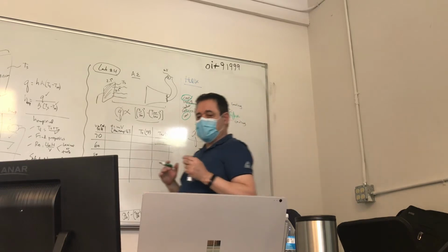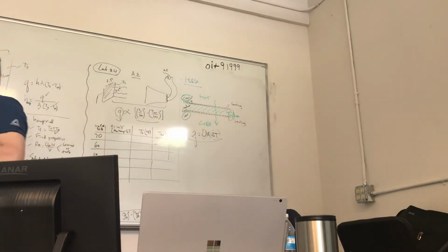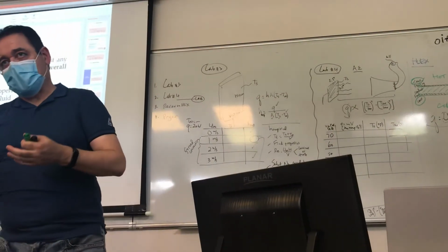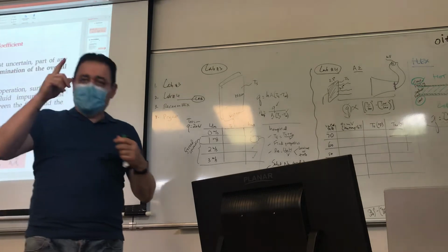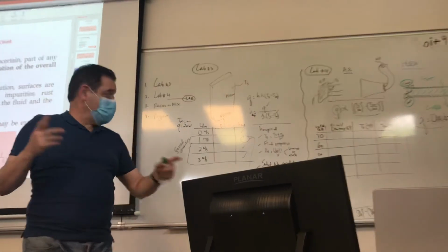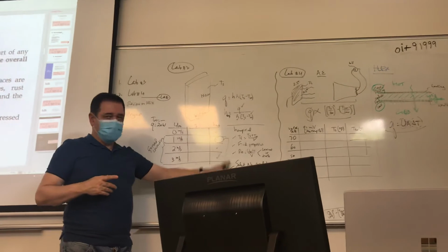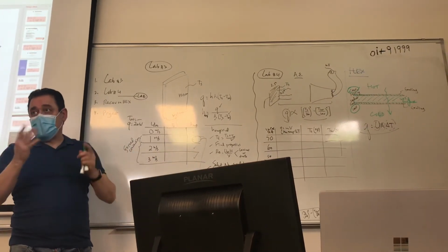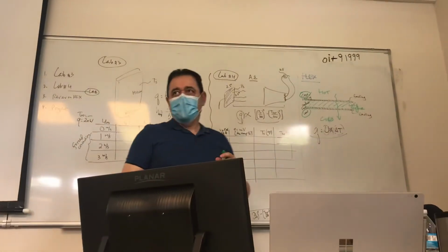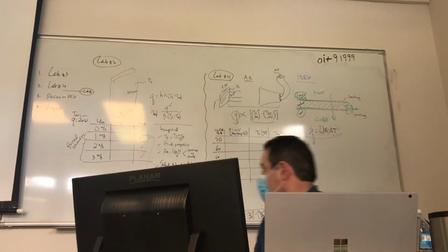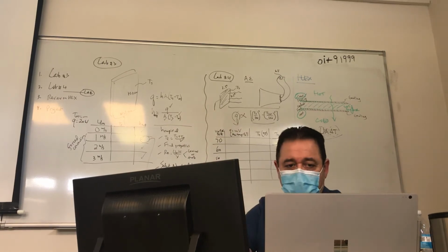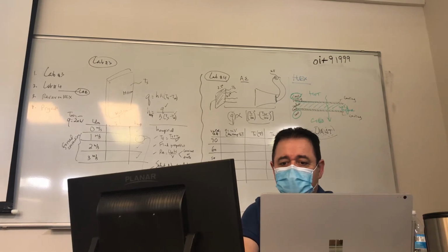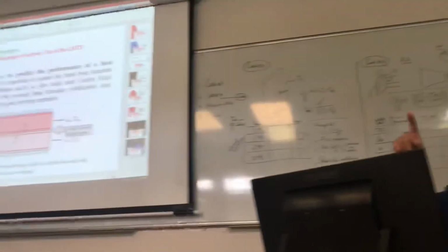So a heat exchanger problem really reduces to again determining h, by looking at whether the fluid is laminar or turbulent, and then choosing the appropriate Nusselt number. This part still applies for heat exchangers, whether you're doing h_i or h_out. So it's the same stuff, it's that stuff back there. So that's the overall heat transfer coefficient, to figure out what your U is, okay?